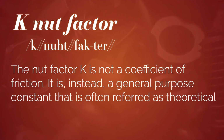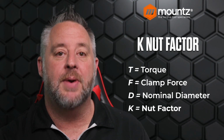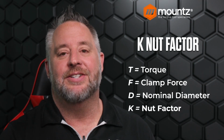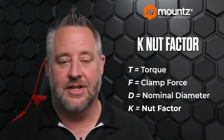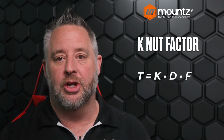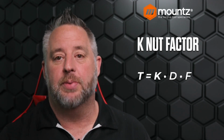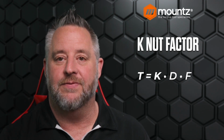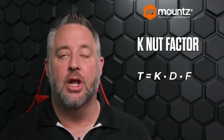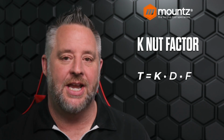But using the nut factor makes it easier to figure out what the correct torque might be for an application, instead of trying to calculate the entire coefficient of friction. And so this makes our formula a little bit easier. Our torque is going to be equal to the K-nut factor multiplied by the diameter multiplied by the force. So this is a little bit easier to deal with as it relates to formulating the actual torque value.